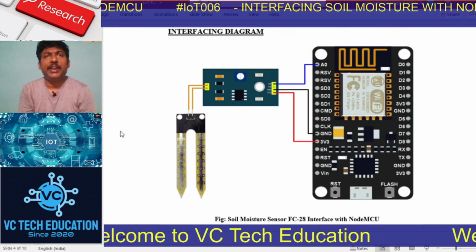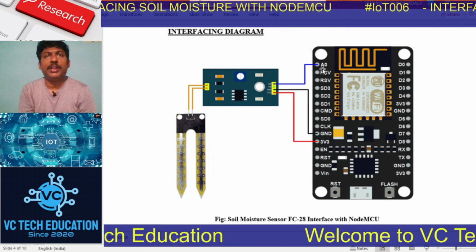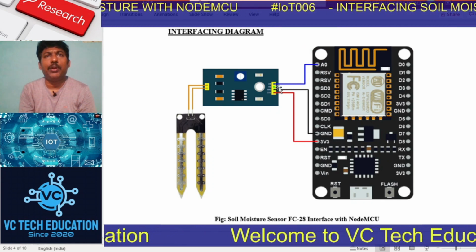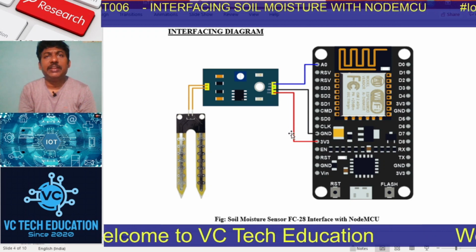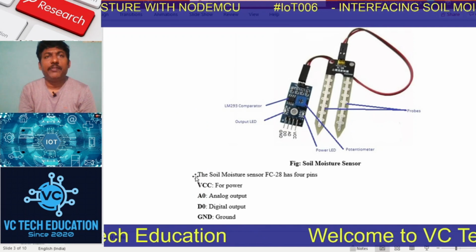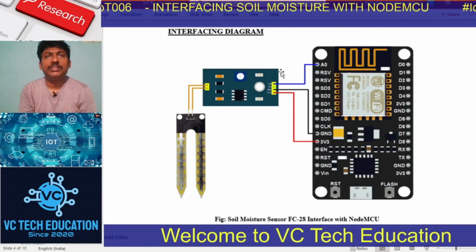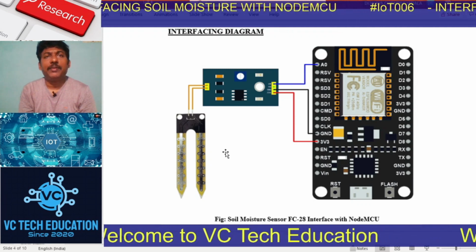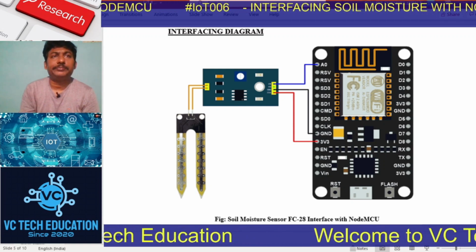So how are we connecting this to the Nodemcu board? This is the Nodemcu board. Here AO will be connected to the AO pin, ground will be connected to ground, and VCC will be connected to the 3.3 volts pin. So this is all about the connection between the sensor and Nodemcu.